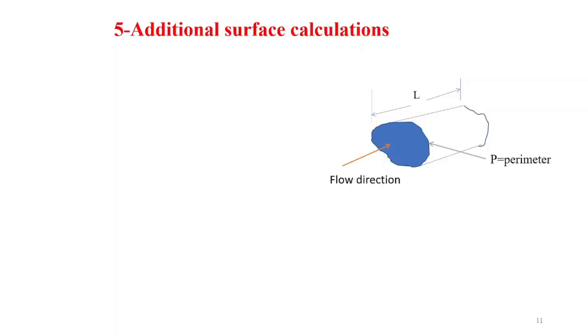understand. The free flow area is the cross-section area of the flow. We call it AFF, where FF means free flow area. The heat transfer area actually is the perimeter times the length. If we consider this geometry, this will give you the heat transfer area. So we now know the free flow area, which is the cross-section area of the flow.